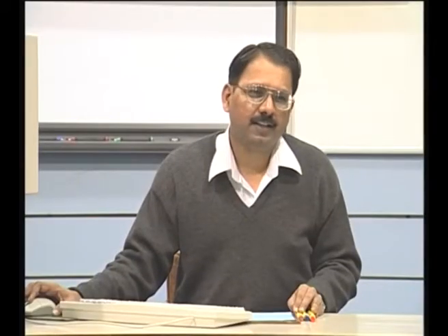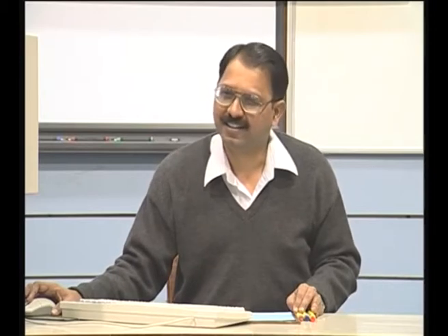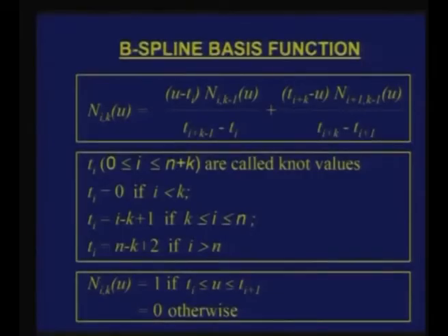Now, let us look at how these basis functions are defined. The expression looks a little complicated, but it is not as complicated as it looks. Any particular value of a basis function N_i,k is given by this mathematical expression. Suppose we take the earlier example of n is equal to 5 and k is equal to 3. What are the n values which I need to evaluate?